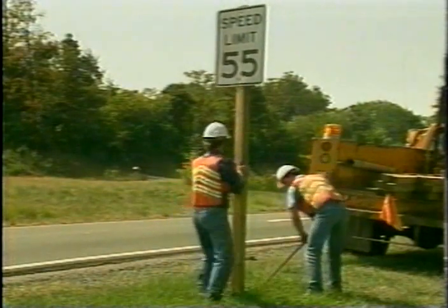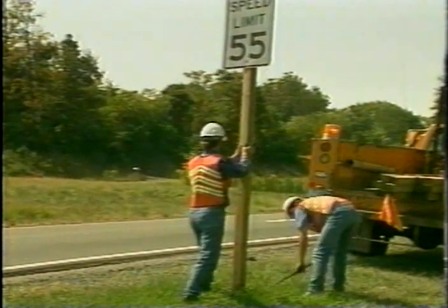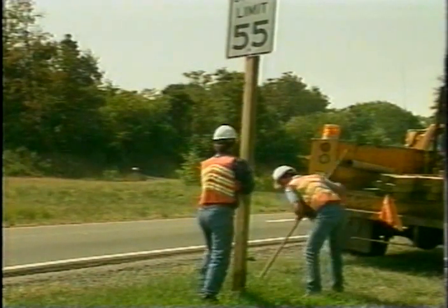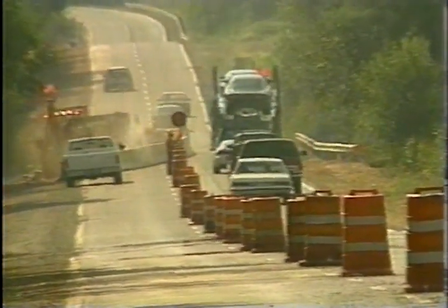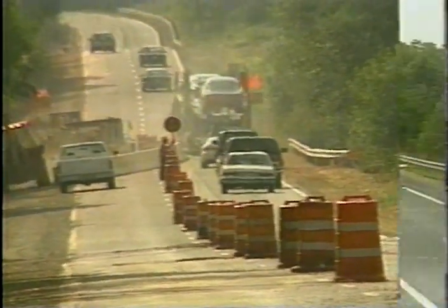Then, remove any existing devices that will be inappropriate once there is a work zone, because they might confuse or contradict work zone devices. Next, install pavement markings, signing, and channelization devices such as traffic cones or barricades. Remember, they must be effective during nighttime and bad weather. If special conditions mean none of these devices will be effective, then use flaggers.